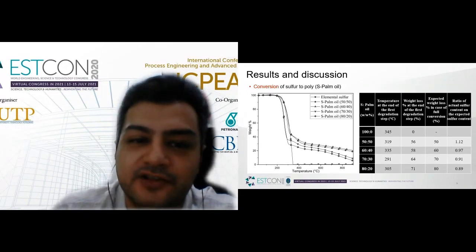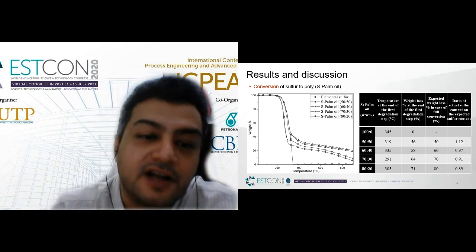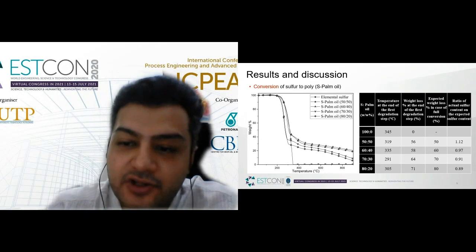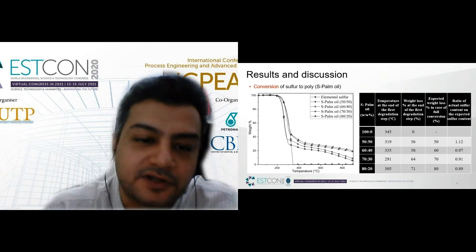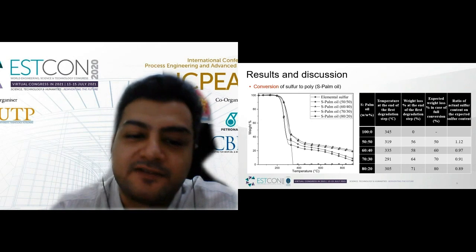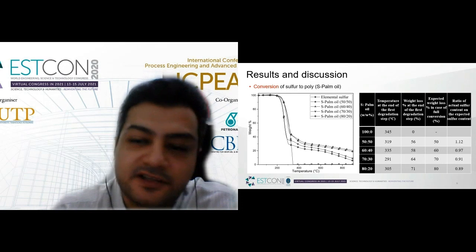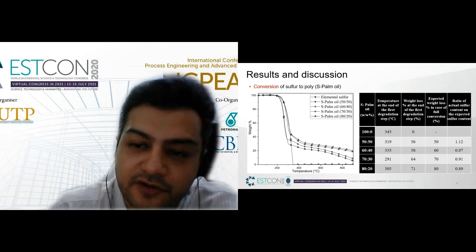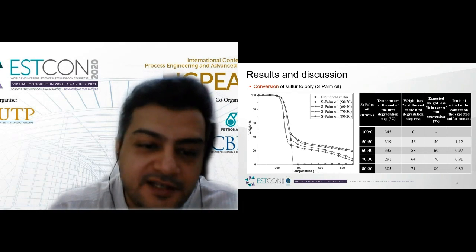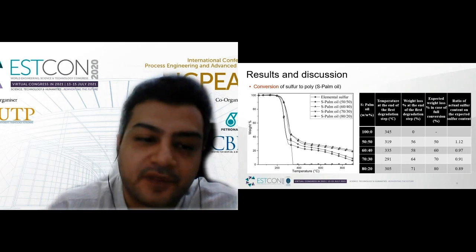The ratio of the actual sulfur content over the initially added sulfur percentage is considered an indicator of sulfur conversion compared to that of palm oil conversion. A ratio higher than 1 in the case of the 50-50 polymer shows that a big portion of the unsaturated section of palm oil has not taken part in the polymerization process and was wasted in a sludgy phase that is formed on top of the product. However, in the case of the other polymers, by increasing the initial sulfur load from 60-40 to 80-20, the conversion of sulfur decreased compared to that of palm oil.